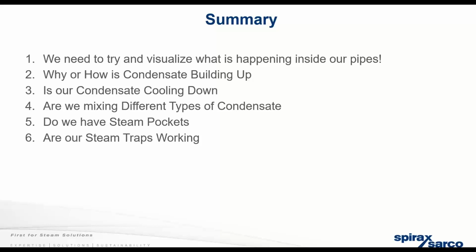Do we have steam pockets forming in our condensate system? Yeah, maybe, maybe not, but we need to have a look at that. And are our steam traps working? Failed cold steam traps. If they should be working, they gotta be hot. Our first check is to make sure all our steam traps are hot.